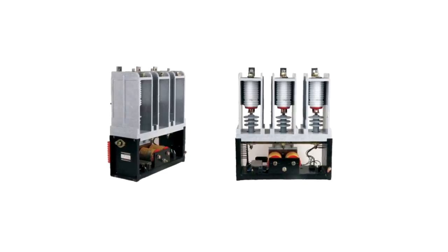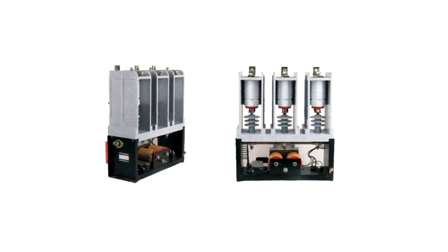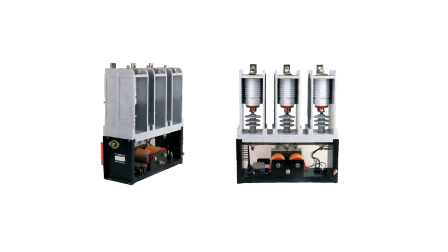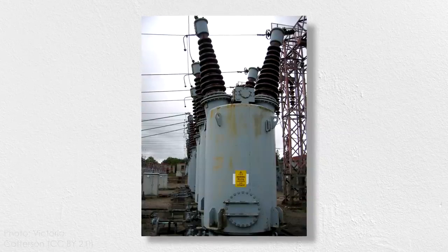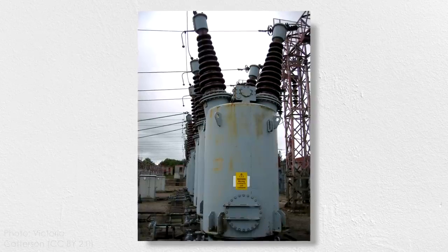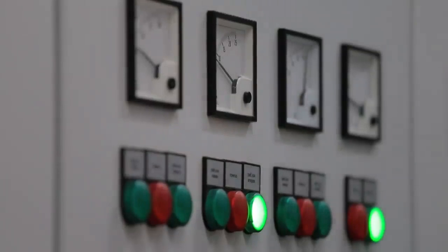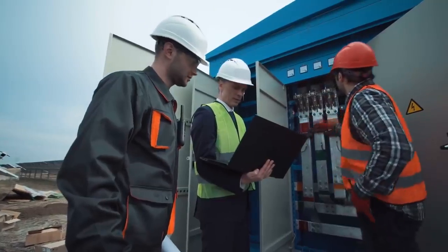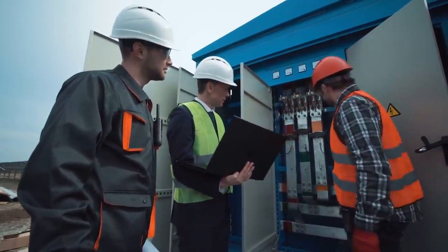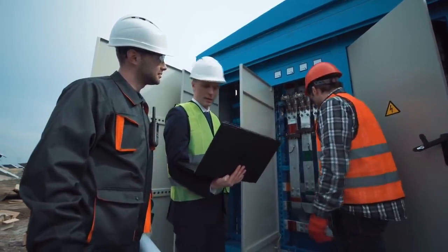For lower voltages, the circuit breakers can be located in a sealed container under vacuum to avoid electricity conducting in the air between the contacts. For higher voltage, breakers are often submerged in tanks filled with non-conductive oil or dense dielectric gas. These breakers give grid operators more control about how and when current gets interrupted. Not every fault is the same, and sometimes operators even know about a disturbance ahead of time and can trigger breakers early to prevent cascading failures.